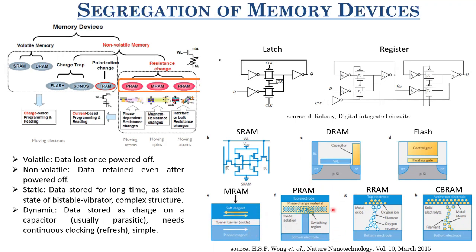Phase change memory, pretty good. You would wonder that this phase change memory is no longer emerging, because in 2010 itself, the N series and E series phones of Nokia were using phase change memories. So it's not something which is emerging, but the main problem with these devices is the large cell current that is required to melt this phase change material and then quench it again. Quenching doesn't require energy; it's only required in melting. So melting is a highly energy-draining process. So you need large cell currents. RRAM's major problem is variations. Otherwise, this is one of the most promising candidates for future memory technology.